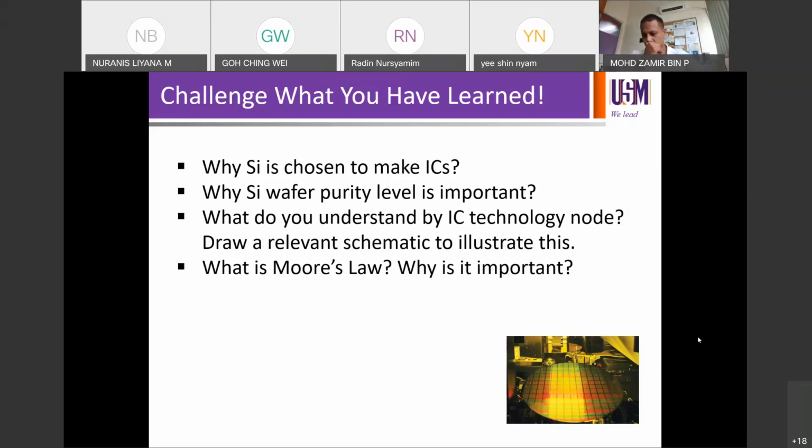Boleh kah silicon kita exceed 1000? 900 C, okay. So it's actually in that region. It can stand up to 1000, 1050 max, typically in a manufacturing process, especially when we talk about doping, oxidation, right? So you can't go near to 1400 because silicon will melt at 1400 degrees C. Certainly not beyond 1400. Right.